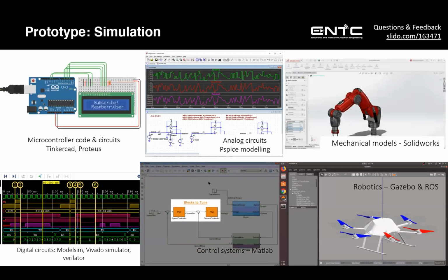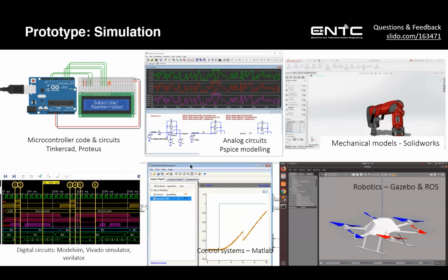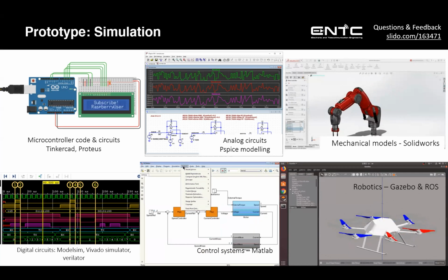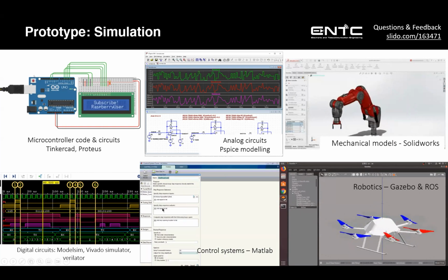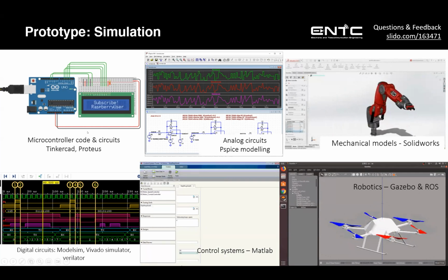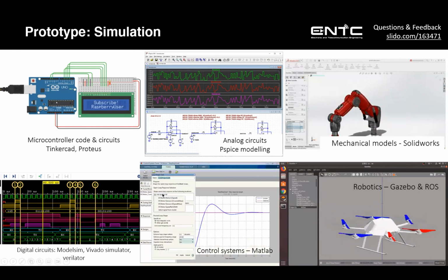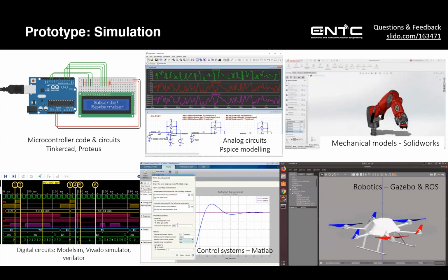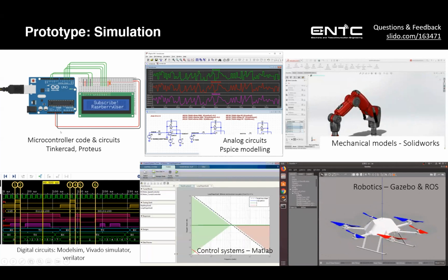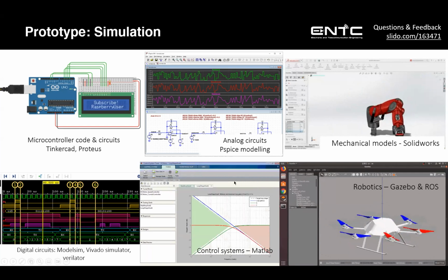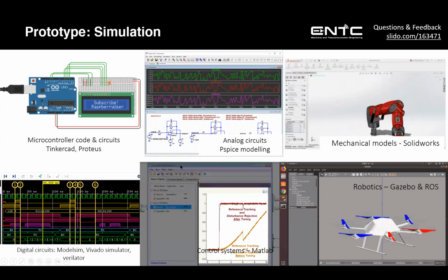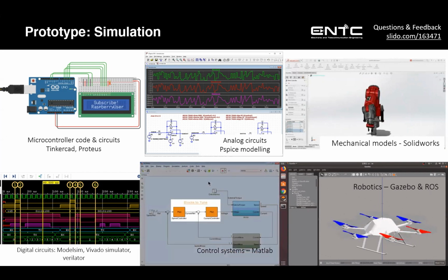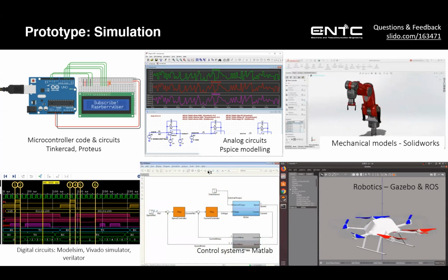Okay. So the next part is the first part of prototyping. Before you even go into building a full-scale prototype, what you can do is simulation. There are different types of simulations, and we will be following this methodology throughout this course as well. The very first thing we'll be building is using an online simulator, where we write our code because you can test it very quickly. You don't have to upload it offline, you don't have to put wires together. You just open a browser, connect an Arduino, put in some virtual wires, write some code and check whether the thing works. That's really fast, and that is the very first step. Once you get that logic correct, then we will go on and build the circuit in the real world, then build it as a PCB, and that way we will progress.